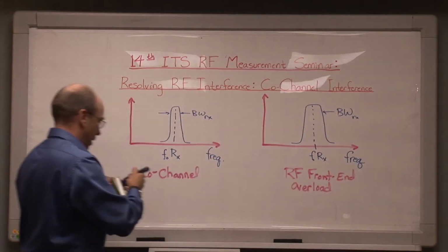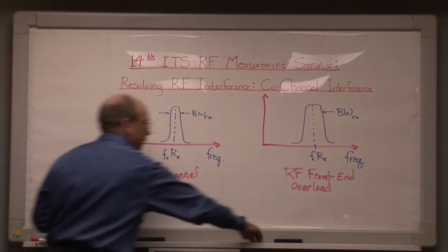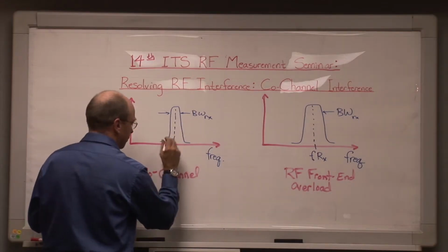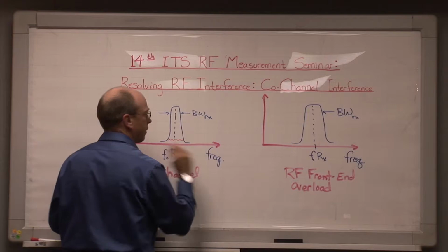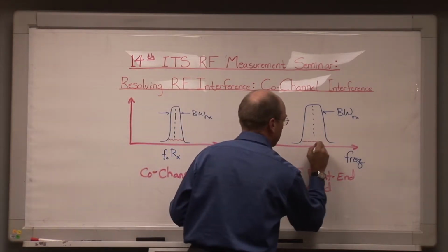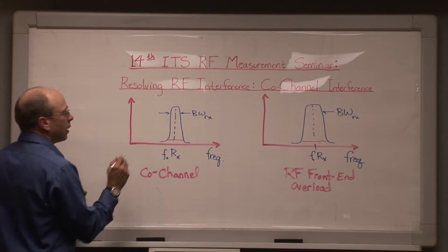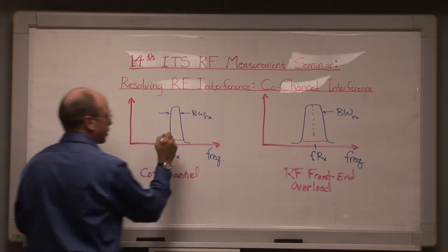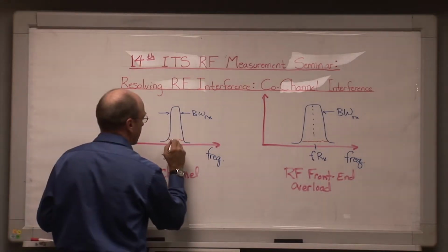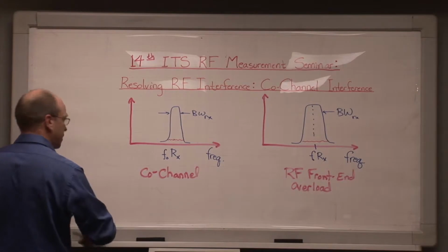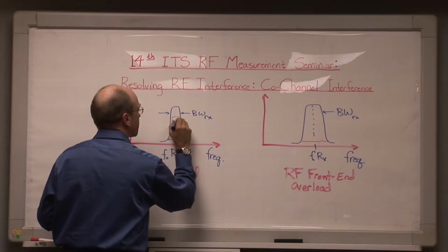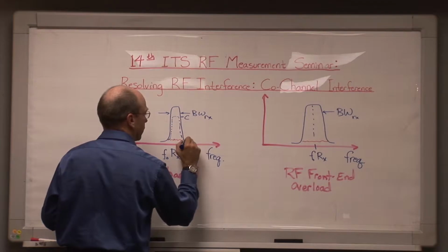bandwidth of the receiver, like so. And either we have interference energy getting into the receiver. Oh, in fact, I'll back up. Here's the receiver's internal noise floor down here, like so. And if this is a communication receiver, then it's picking up a signal that has some desired signal-to-noise ratio or some desired carrier-to-noise ratio. So we'll draw the receiver's desired signal inside its bandwidth as looking something like this. Here's its desired signal, and it's got some particular carrier level relative to its noise level.